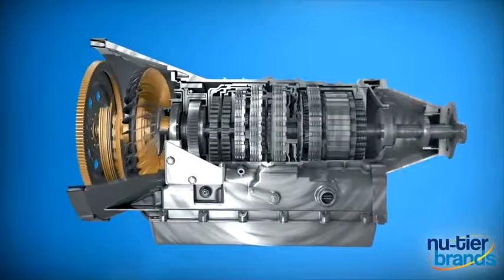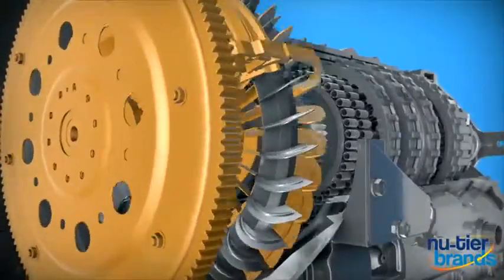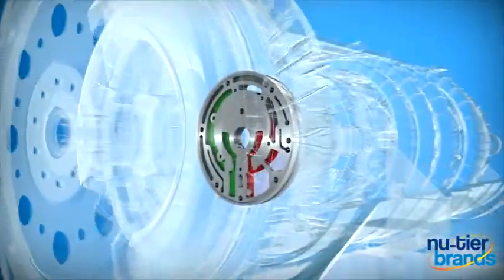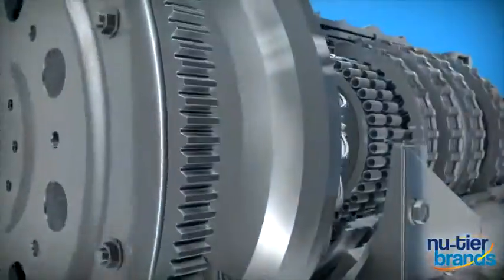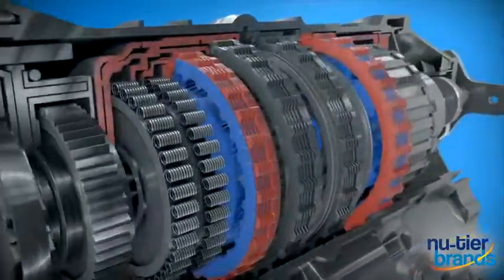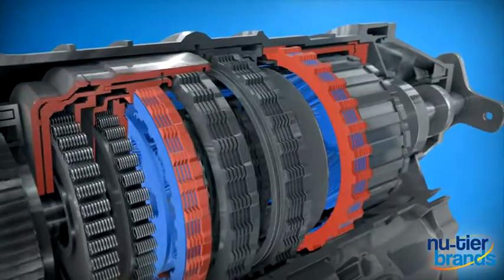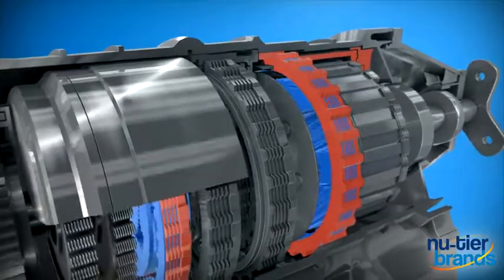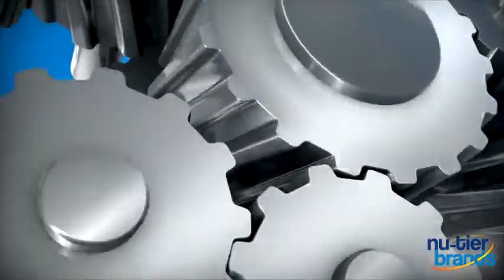Now, let's see how these components work together. At idle in park, the pump components spin, providing the pressurized fluid needed to operate the transmission. When the vehicle is placed in drive, clutches connect the gear set for first gear to the wheels, and when you release the brake, the car begins to move. The gears are engineered to withstand the extreme pressures and wear of continuous high-speed operation.